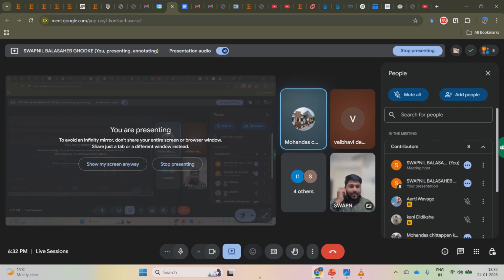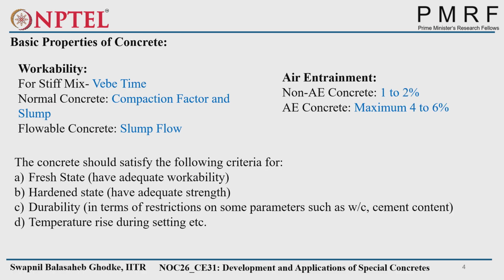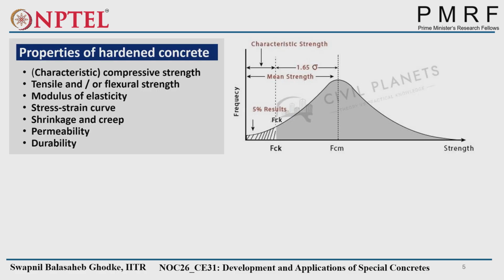Yeah, water cooling is used. I also visited one of the chilling plants. Most of the big construction companies use a chilling plant, using cold water to avoid a higher amount of heat generation. Because of that, cracks will not appear on the surface or on the core.